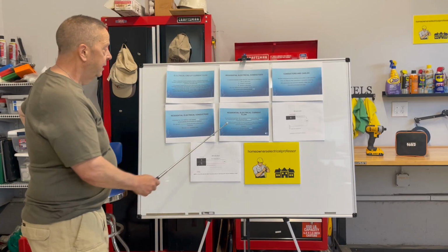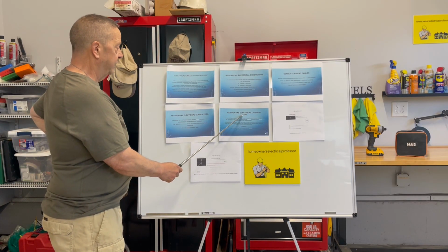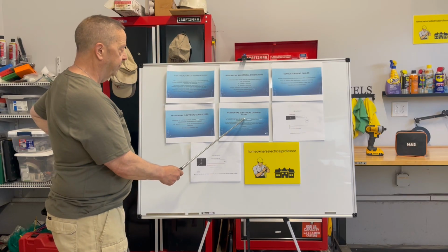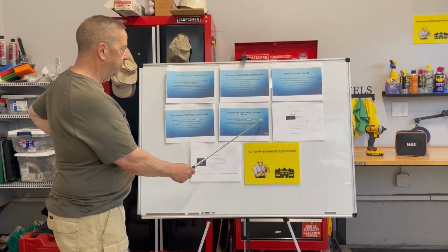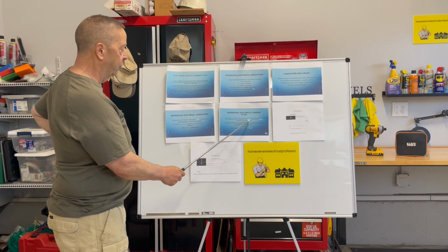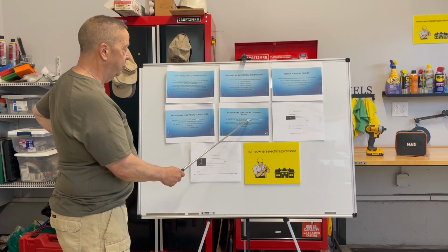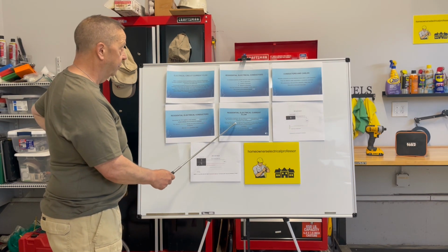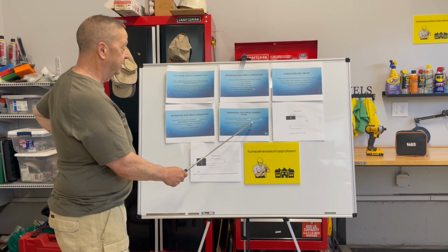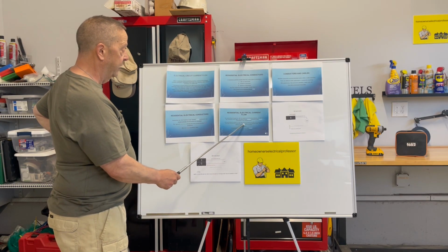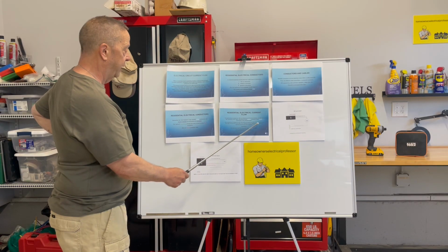A summary of residential electrical current flow. The normal flow of current in a 120 volt circuit is out of the circuit breaker through one hot conductor to the load and returns on the neutral conductor to the neutral connection in your electrical panel. The normal flow of current in a 240 volt circuit is through one of the hot conductors to the load and returns on the other hot conductor to your electrical panel. More on panels and circuit breakers later.